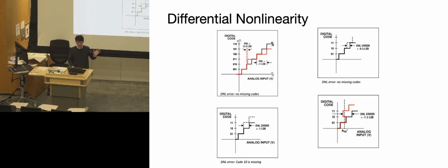This is usually caused by hardware. For example, the voltage dividers you used, or the divider types of DAC configurations you use, where the resistance you chose is not accurate enough. Depending on how you connected them, the accumulated error can be a little bit random. Yeah, this is a little bit hard to get rid of. Usually you just test all the values or you switch to better hardware.